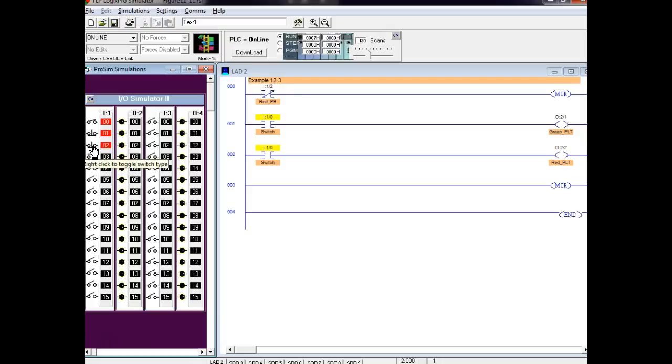Something's going on. They make it sound like this is a stop. We use these for e-stops, so we're supposed to turn off. It's a closed button too, so in the PLC I think it's got to be the same way, if that's going to be a stop button.